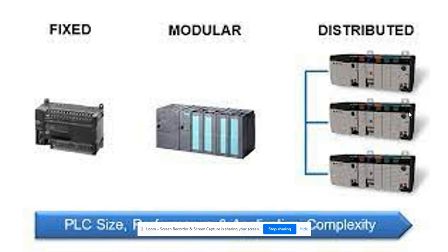Okay. So the third one is the one you can see in that diagram. It is called the distributed programmable logic controller. It is in a setup where there are complex processes to be controlled. One module, for example the input module, you can find in one room. The CPU module, you can find in the next room, for example. And the output module, you can find in another room. So it is called distributed because the modules are distributed in various places.